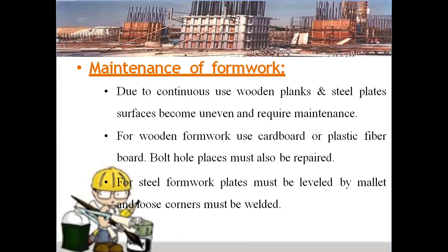For steel formwork plates, they must be leveled by mallet and loose corners must be welded. If the steel formwork is used to cast concrete, these steel formwork plates must be leveled using mallets, and the loose corners where welding is needed can be welded.